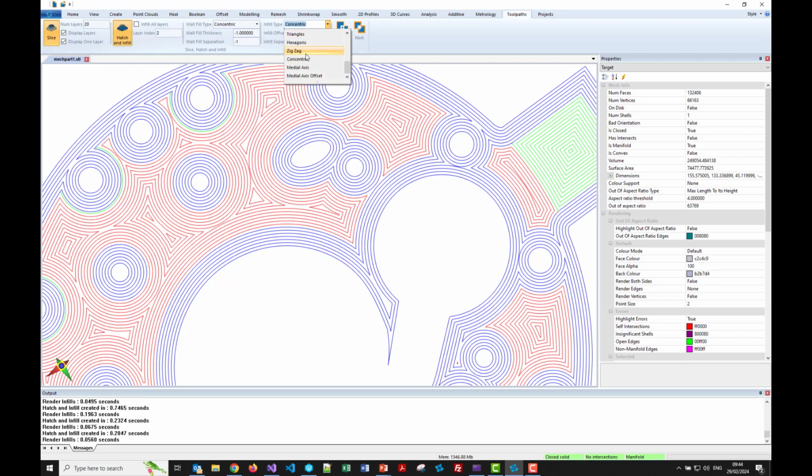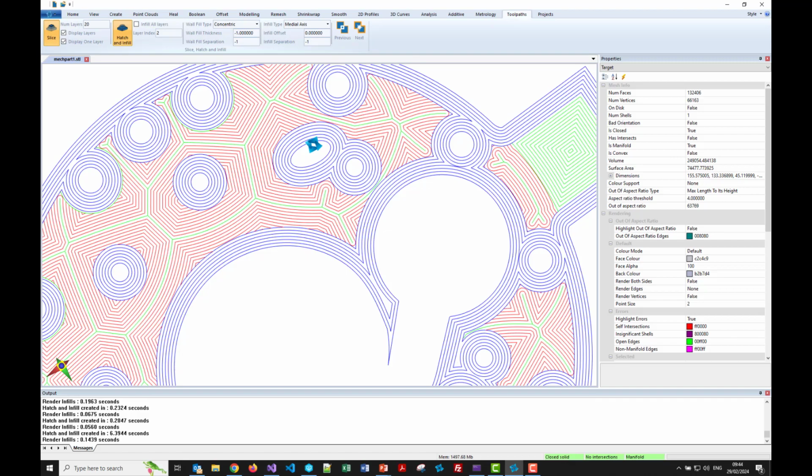That's why we added the medial axis approach, which is an alternative approach. Takes a bit longer to compute. So the medial axis, I'm going to do a more detailed blog on this video, but it's a line that joins the sort of, it's like a center line, a skeleton if you like. So any point on this line is equidistant from the profile. So you can see that's from there, and there. And one of the key features it has is it will join bridges. So you can use it to guarantee that material is going to be deposited even in very narrow regions.